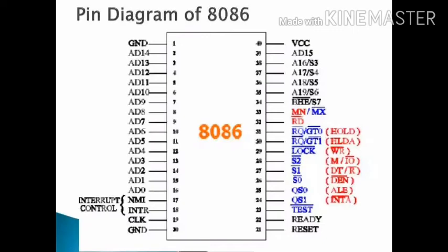of the machine cycle. So if 8086 outputs a logic 1 on this pin, it means the buffers are used to transmit data from 8086, and if 8086 outputs a logic 0 on this pin, then the buffers are set up so that 8086 can receive data from the buffers. So it will indicate whether the 8086 will transmit data or data from the buffers is received by the 8086.